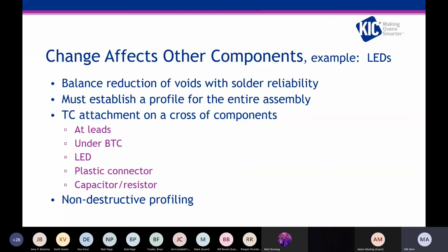And one of the problems, of course, with profiling is it's potentially destructive. So there are methods of attaching thermocouples that are non-destructive. We did a study with Rochester Institute of Technology on non-destructive profiling on BGAs as an example, whereby they created a calculator so you could put a thermocouple on the top of the BGA and know what the temperature was at the ball without doing destructive profiling. And that's available on our website, and you're more than welcome to download that. Some people have used that as an extrapolation also if they're doing bottom terminated components to understand the temperature at the ball without destructive profiling.